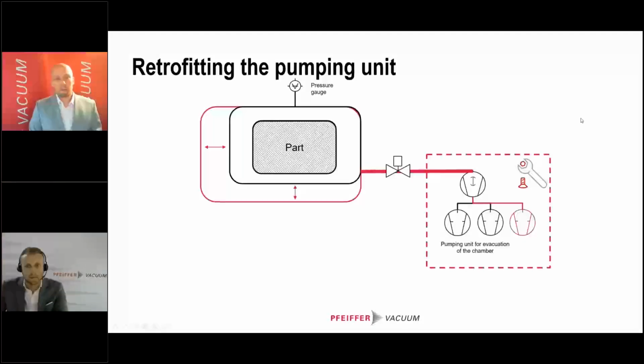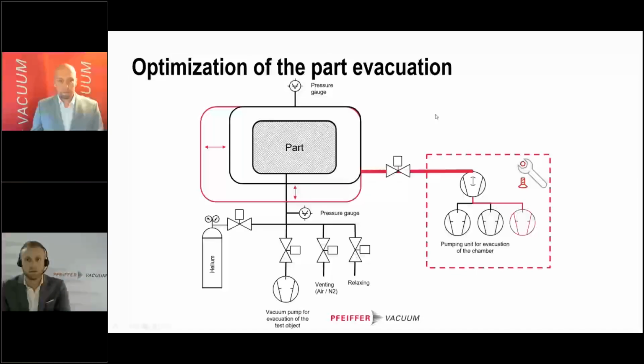This is only the part which considers the chamber evacuation, but you can also optimize your pump down time or your overall process time when you spend some thought on your part evacuation. Because during the initial pump down, before filling the part, often the part evacuation is done in parallel.